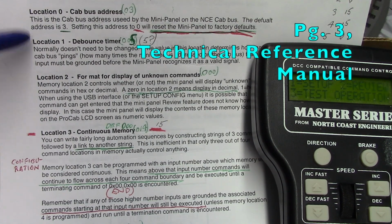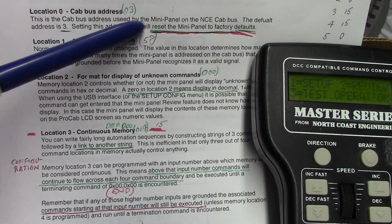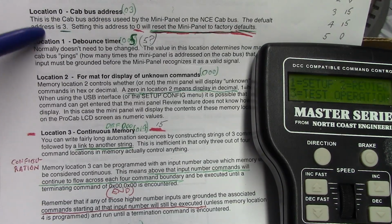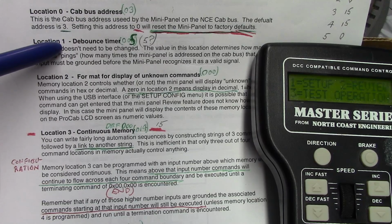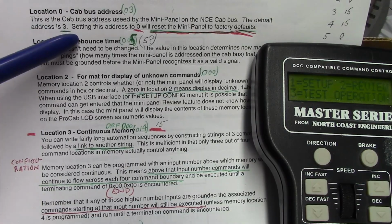And there's a couple important ones, and I'm on page 3 of the mini panel technical reference manual. The writers at NCE can probably explain this better than I can, so I'm just using their work. It just says location 0 cab bus address. This is the cab bus address used by the mini panel. The default address is 3, and remember it's got to be 3 when you're using it with a power cab. If you're using it with a Powerhouse Pro, or you're daisy chained on a power cab system, you can put it to something else, but it's got to be 3 if it's plugged into the power control panel like we were earlier.